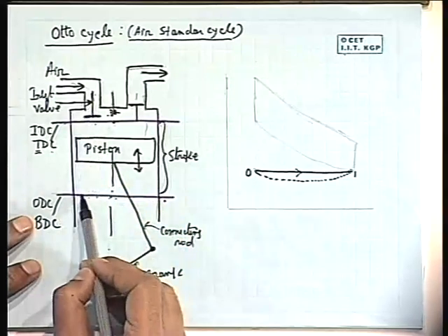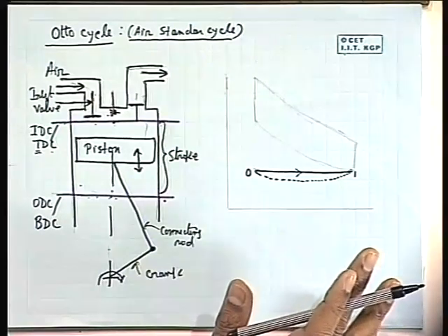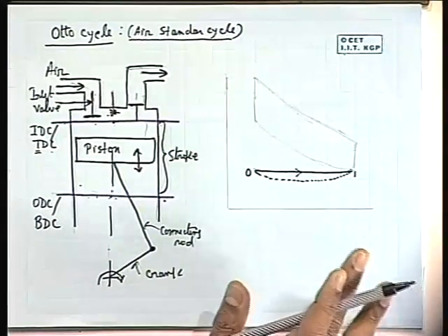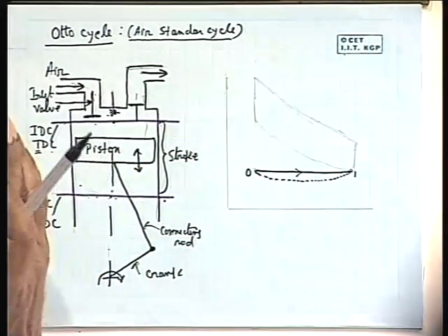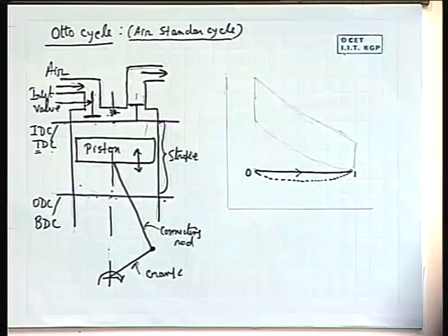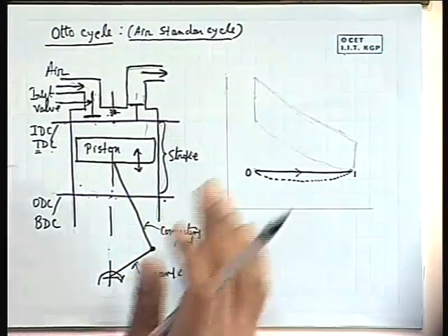Now you consider a situation where the valve is closed. It starts closing much before that, but I am not going into these practical things. There are certain times for closing and opening the valves, known as valve timing, which is set to get the maximum possible power. You have to open the valve when opening is most useful, and close the valve when closing is most useful from the viewpoint of the operation of the IC engines. That I am not going to describe.